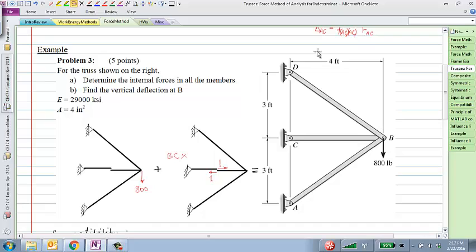For a two-dimensional problem, the total number of equations is, of course, the sum of forces in x, y, and moment equal to 0. But that holds only when your structure is not a mechanism, right? If I disconnect these three supports here, this structure by itself cannot hold its shape. It's a mechanism. Ever heard of that? So in this particular case, what you would have to do is disconnect all these three members separately from each other. You would have, in that case, three separate structures. 3 times 3, you would have a total of 9 equations. And the number of unknowns would be 6 reactions definitely, but there would also be 4 internal forces between all these 3 parts. And I can show you the details, but maybe I want you to figure out how that would work.